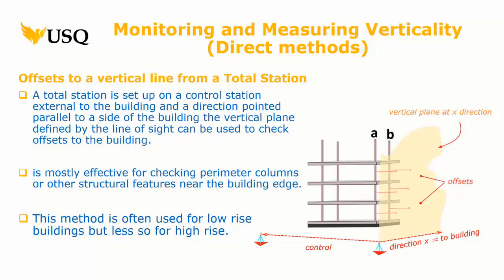And also for deformation checking because fairly easy to do, relatively easy. And a little bit like leveling, if you remember back from when you first learned leveling in surveying A, right? Which I'm sure you learned it very, very well, is that when you hold it out from the building, how do you know that you're right next to the building? What you do is you move it, right? And the shortest distance will be the answer. You know, exactly like a staff. You know, doesn't matter where you sway it, the lowest reading will be correct.